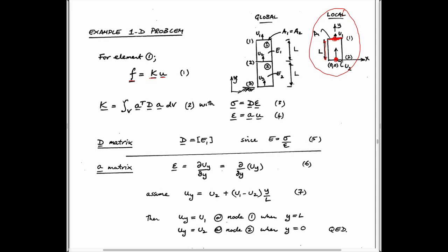But for now, all we have to think about is how we get the equations for this. We know that our stiffness relationship comprises these two matrices, which are the A and the D matrices. This is our constitutive relationship, which is Hooke's law, which says that stresses are related to strains through this. And so if this is the case, then Hooke's law would just be Young's modulus.